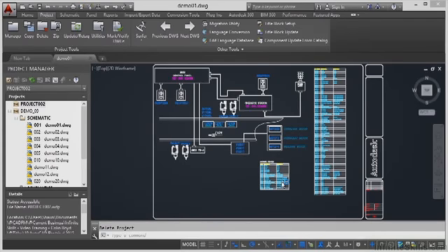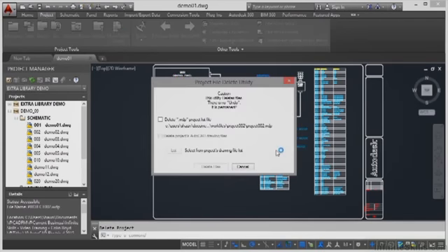So I click on Open, like so, and you'll see, caution, this utility deletes files. There is no undo, and it is permanent. Absolutely. When you delete a project, it is gone. It deletes everything. And also, you want to make sure that you do delete the WDP file as well.